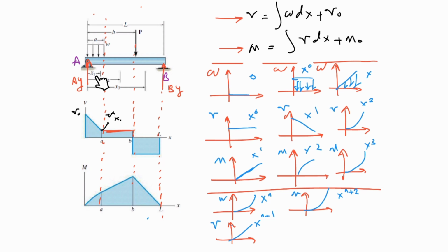You just need to consider the initial value, meaning that here I know I have an initial value because of this jump up. This is a distributed load and it's negative. The effect of this on V is going downward with a line reaching here. How to find this? See how much the area is here, subtract that, get to this point, and stay there, because this is 0. And here I have a jump shifting down, here nothing, stay there, go up.